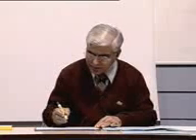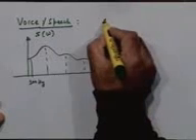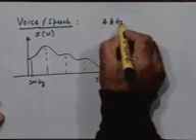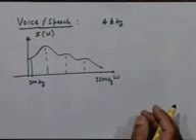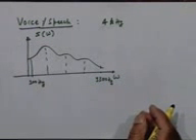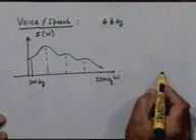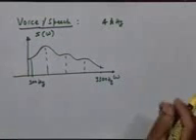That 4 kilohertz includes some guard band, some additional frequency band, to make sure that we don't lose anything, right? So typically, the bandwidth of a speech signal is regarded to be less than 4 kilohertz. But I must mention, this is not the actual bandwidth of the speech signal, right? The actual energy plot extends beyond this and goes on up to about 7-8 kilohertz.